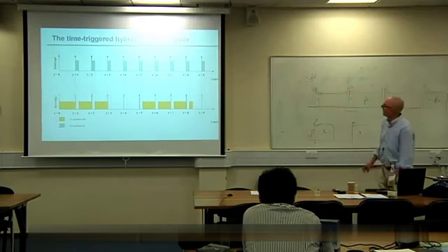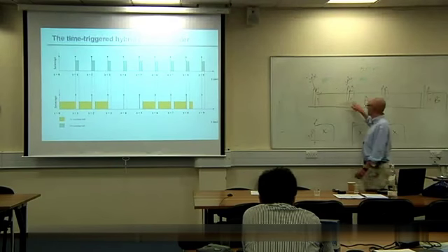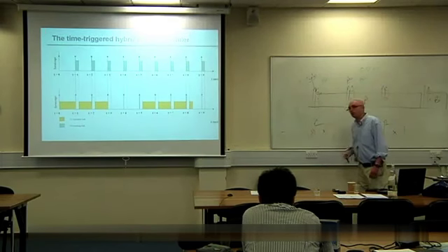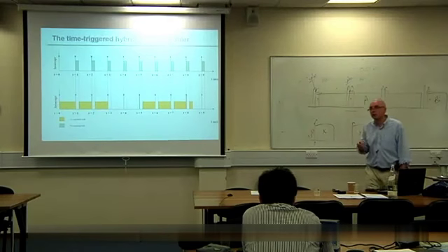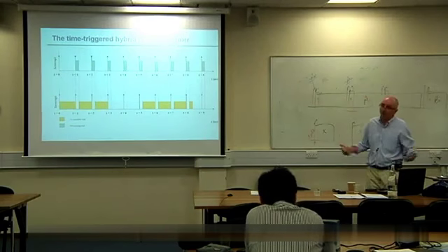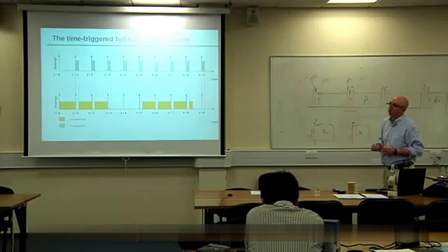The cost is you've lost 0.5%, 0.25% or something of your available CPU time in the system. So you want to make that optional. Maybe you don't care. Maybe you don't need to get jitter levels in that case, in which case don't do it. If you do, you've got it as an option. And you've got it as an option because the system's time triggered. So you know when the next thing's going to happen, so you can get the system into a known state before you get there, and you've got control over the way the system operates.